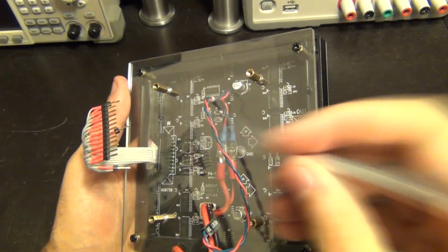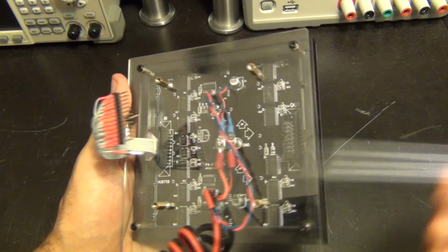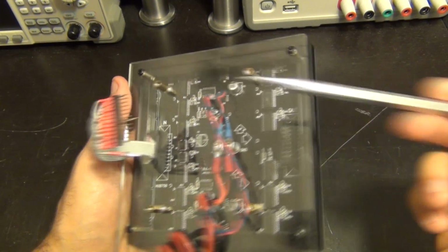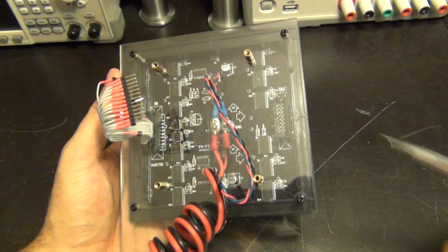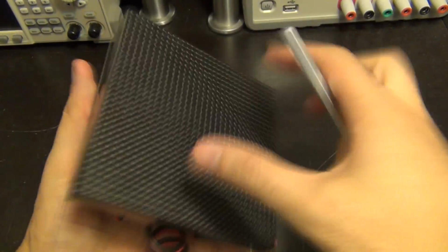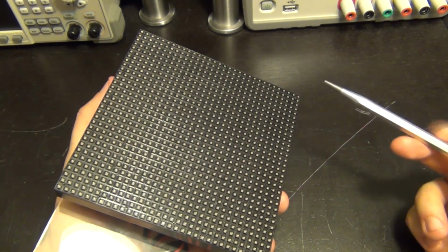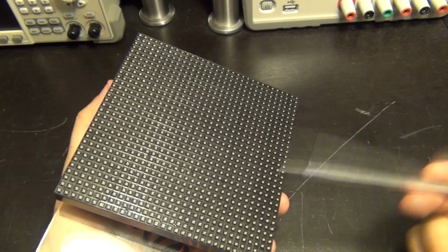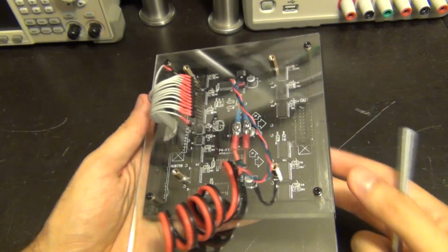Now there is another clever circuitry in there which I would just hint at so that you would keep it in mind. There's actually a rectifier circuit inside this, and that rectifier circuit is connected to the enable pins of all the drivers. If there is no address increments at a certain rate, meaning that if the address of the row isn't continuously changing, it would disable the screen. Now can you guess why they do that? Well, they do that because they want to make sure that if the address isn't advancing and this display is stuck at only displaying one row, it wouldn't be stuck showing that one row, because then it will have too much current and it will damage the LEDs. The current is higher than the steady state current the LEDs would require, because they expect this to have a continuous refresh rate. Therefore, they put more current to achieve higher brightness for shorter duration of time. And that's another thing that LED matrix of course do.